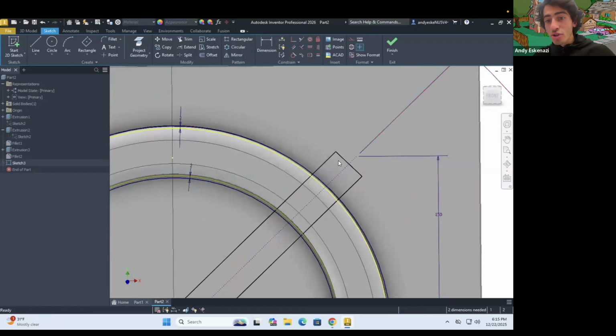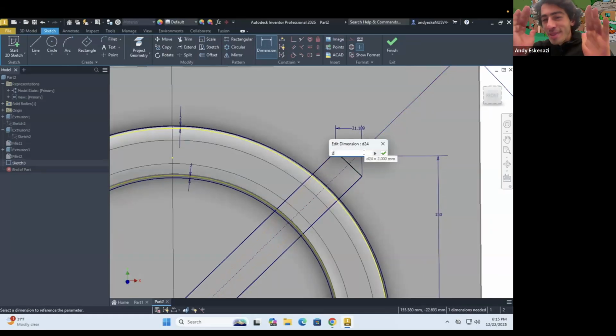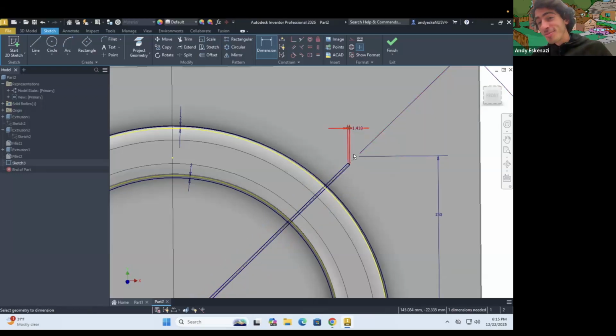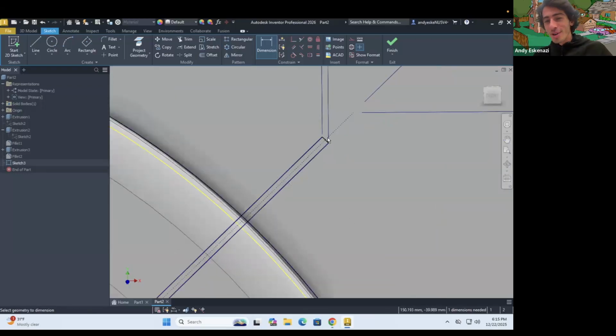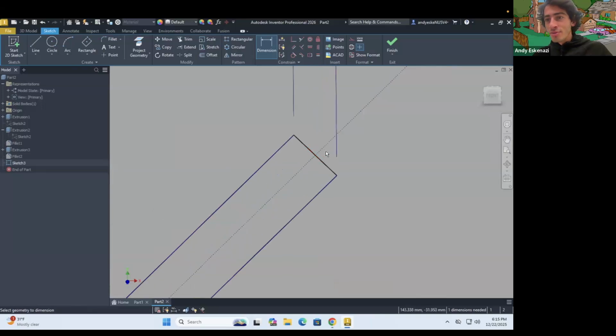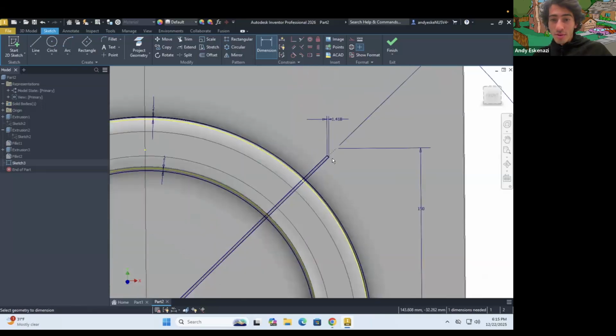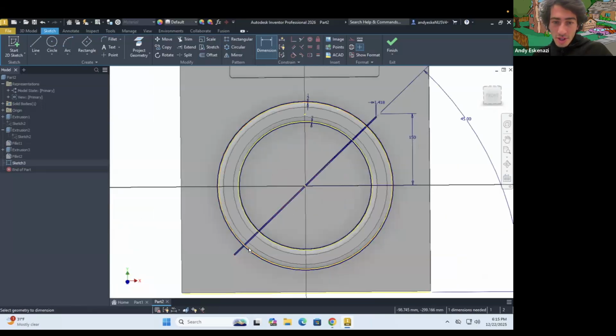So this dimension here has to be equal to 2. So I'm gonna click in there and say, all right, 2. However, because it's only allowing us to define it from that perspective, I can say I want this to be equal to 2 over 1.41. Let's see whether that works. Yes, it does. So it's 1.41. Perfect. That's the particular dimension where I want that to be the case. Very good. And you see that that's fully defined.